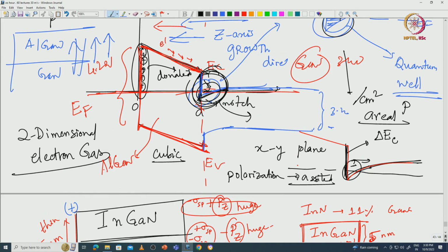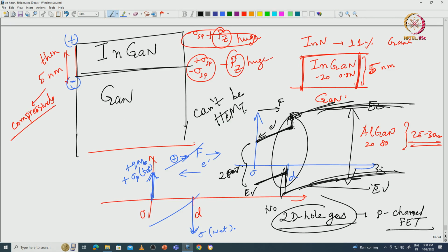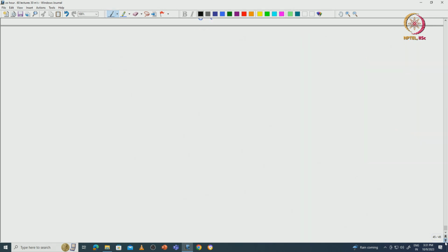Well, it was historically high electron mobility because it was AlGaAs, where there was no polarization, but people used modulation doping, but in gallium nitride we still call it high electron mobility transistor, although the mobility is not as high as in AlGaAs or a traditional compound semiconductor heterostructure. Okay. It is not as high, still we call it high electron mobility transistor. Now, okay. So, now I will only focus on those heterostructures that are more useful or more promising for an RF application. Some of them may not be commercially available, but they have been extensively researched.